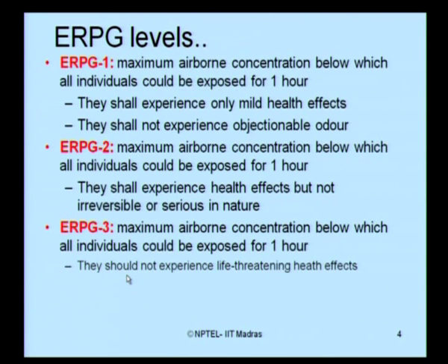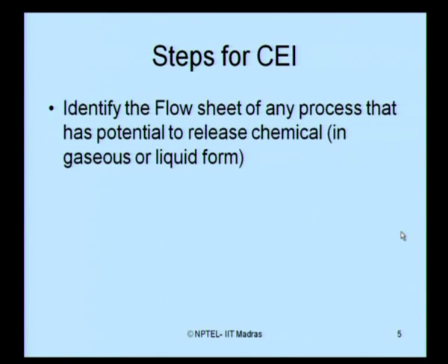If they do not experience such life threatening health effects when exposed to such maximum airborne concentration due to a chemical release for a maximum period of 1 hour, then we call that ERPG level ERPG 3.